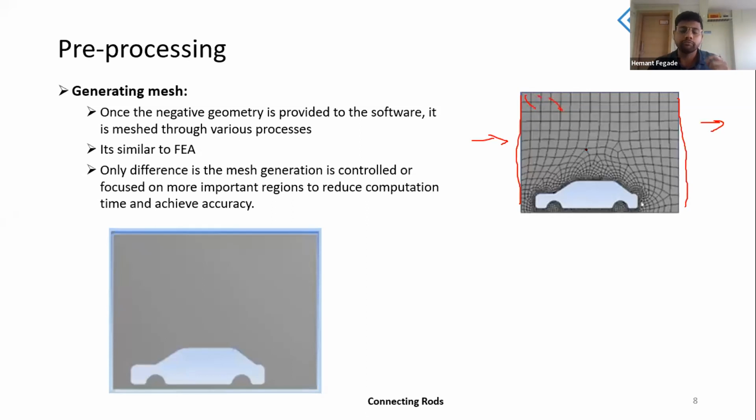So that's why the finer or the smaller the size is, the better the accuracy is. The reason is that the CFD software is going to solve with general numerical methods which are based on approximations and calculations, right?